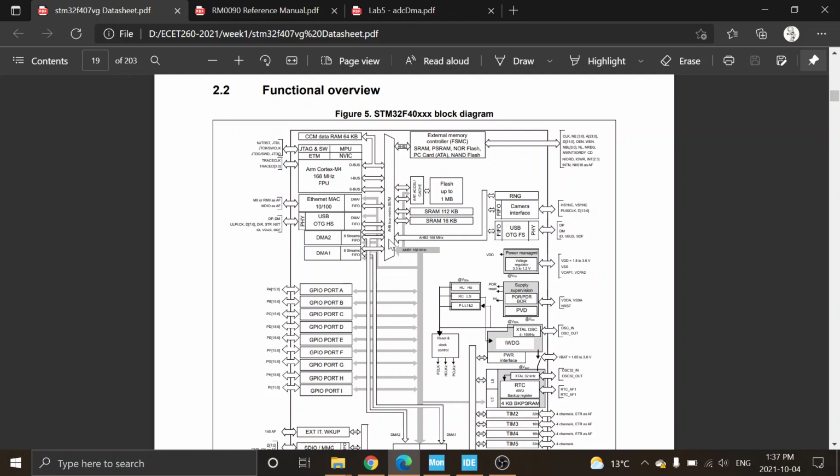And so I have another piece of silicon, just like I also had when I had my nested vector interrupt controller, an external thing to be able to handle different interrupts and provide something to the ARM CPU. We have this extra piece of silicon, and DMA stands for direct memory access, and it's essentially a sequential state machine. You will set it up to say how many bytes you want to move from one place to another and say go, and it does it, without your CPU having to copy this and then write it here and copy this and write it there.